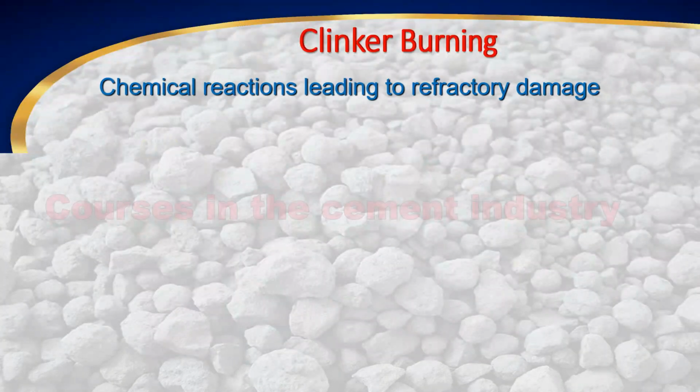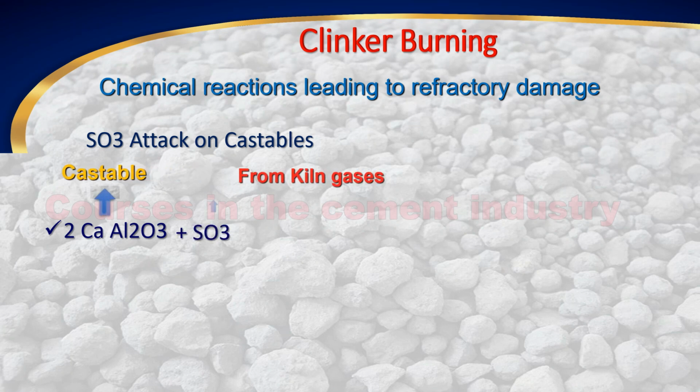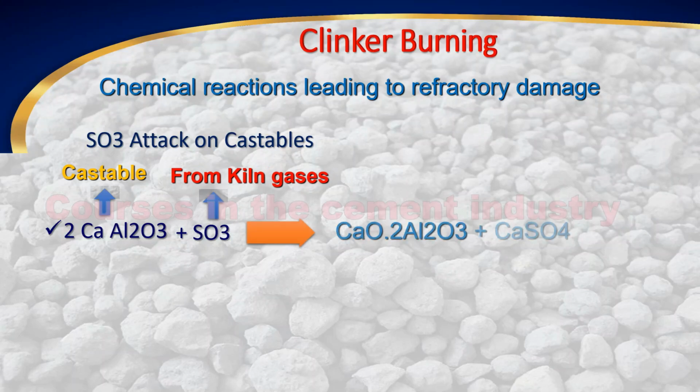Chemical reactions leading to refractory damage. SO3 attack on castables. CaO·2Al2O3 castable plus SO3 from kiln gases. Result: CaO·2Al2O3 plus CaSO4.